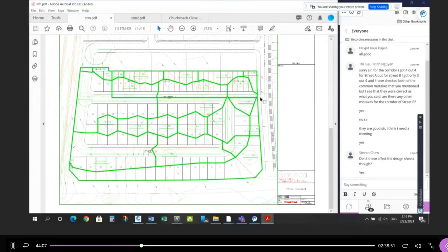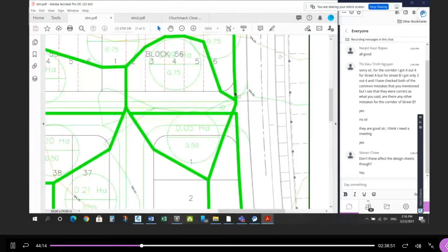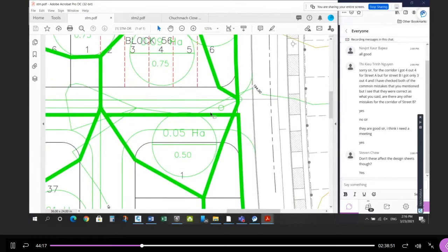And in here, you may or may not have a drainage area for each single pipe. And this is true for sanitary as well, right? If you look here, there's the pipe that goes from here to here. And we take the entire area of these 2 pieces and put it into that pipe. This maintenance hole, all it does is take this pipe and change its direction. So I would take this little piece and just have a 0 area, 0 infiltration or whatever it is, whether it's sanitary or storm, and just pour everything into the pipe upstream.